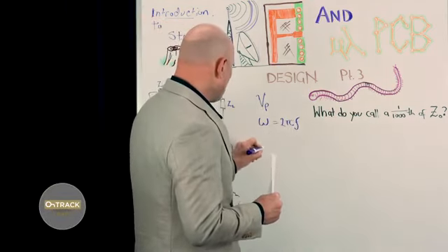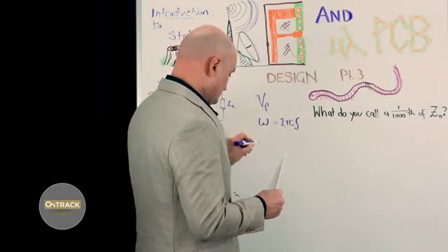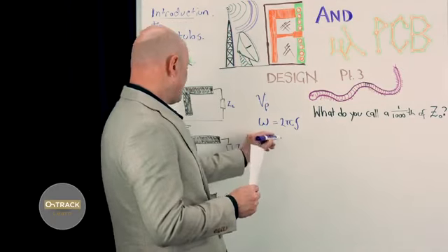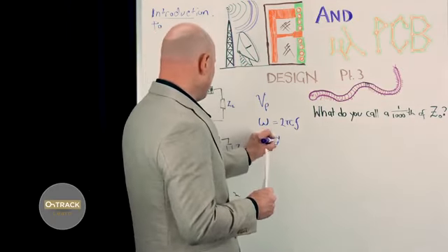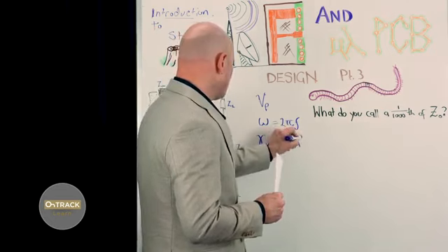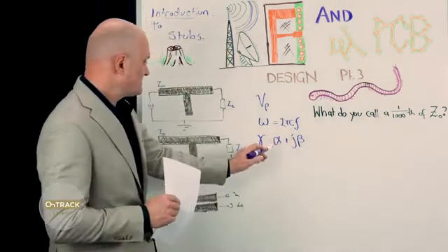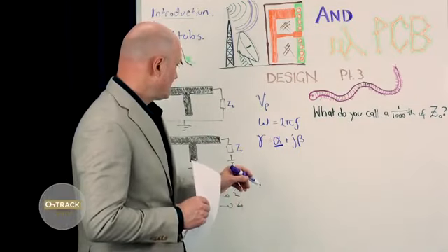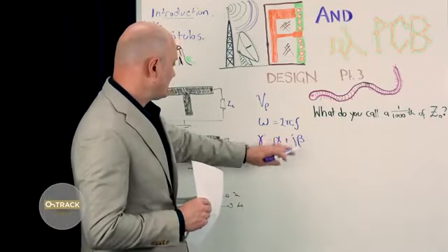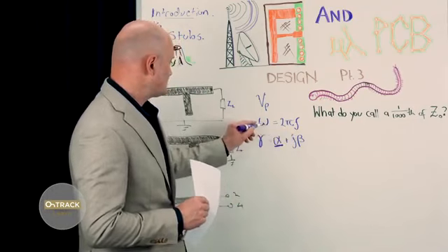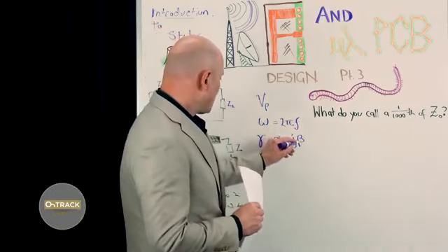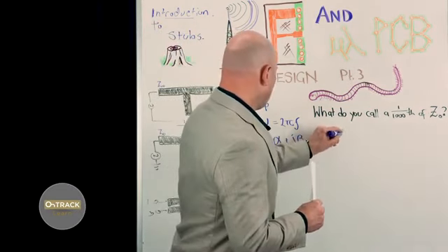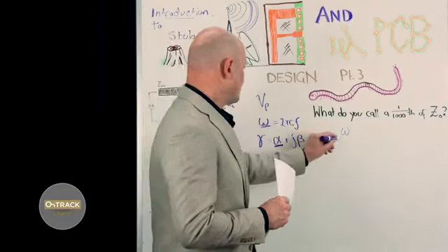And there's this propagation constant, gamma, which is typically alpha plus j beta. We looked at that in an earlier video. So what does this mean? Alpha is our losses, and we talked about losses last time. If you neglect losses, we have this j beta. So what is beta? Beta is our omega over the velocity.